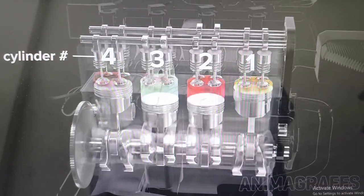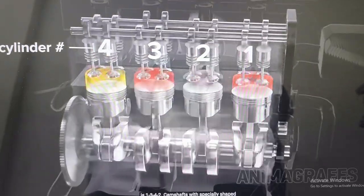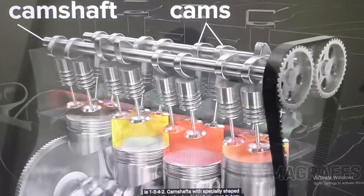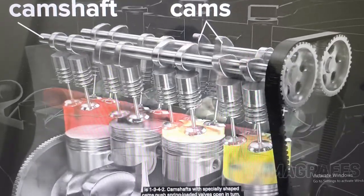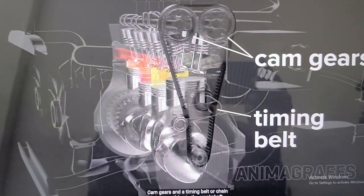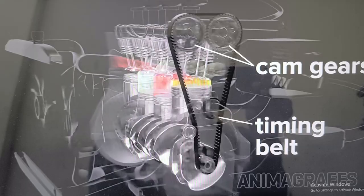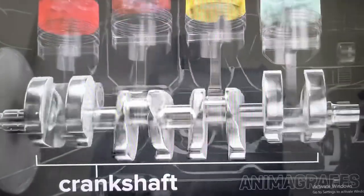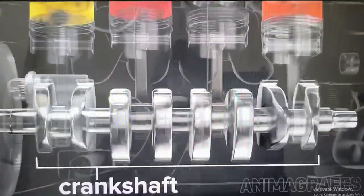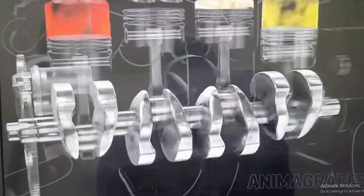Connecting multiple pistons for smooth power delivery, pistons take turns firing. The firing order for this engine is 1, 3, 4, 2. Camshafts with specially shaped cams push spring-loaded valves open in turn. Cam gears and a timing belt or chain link everything to the crankshaft, and it all spins together. The crankshaft translates piston power out of the engine. It has counterweights to balance against the pistons for perfectly smooth revolutions.